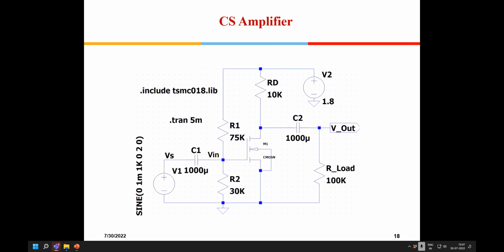Sir, I had a doubt. The threshold voltage VT will always be overcome by this large signal, like VDC, which we are going to get. Yeah, correct. So the bias voltage is essentially to overcome the threshold voltage. And also the bias voltage decides the overall current which is flowing in this, right? The constant current which is flowing in that. Okay, we'll see that design aspect today itself.